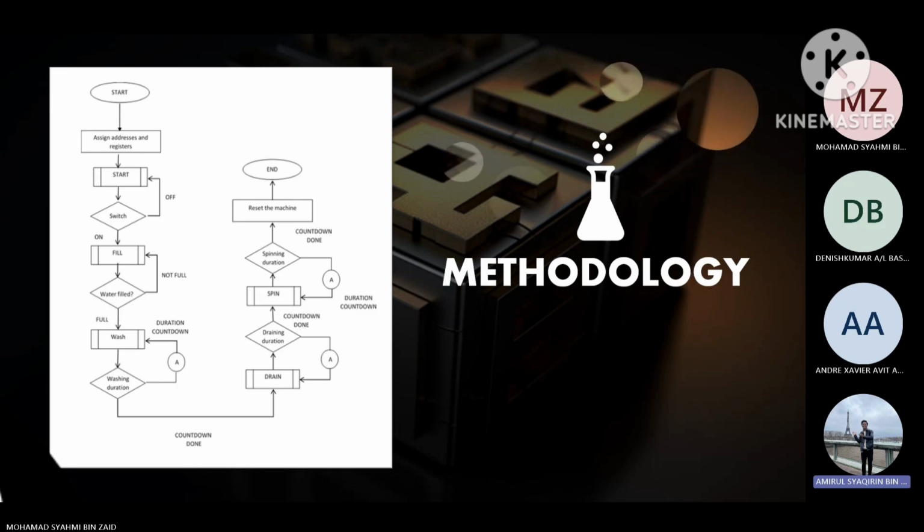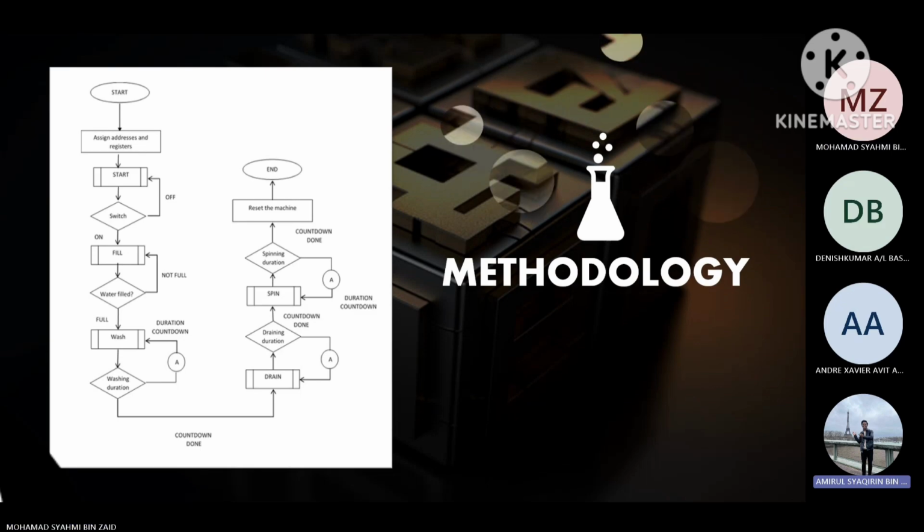The next step is the software goes to the wash subroutine, and the wash operation starts, with WASH shown on the 7 segment display. The duration of the wash has been set in the start subroutine and is called by the address D5.